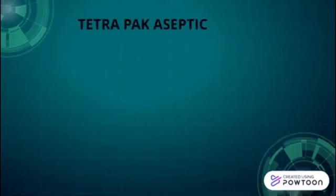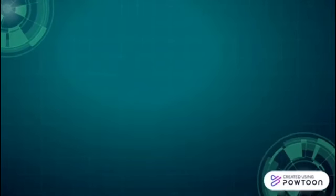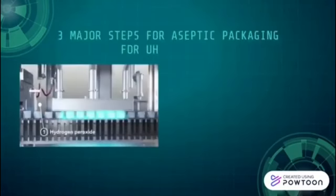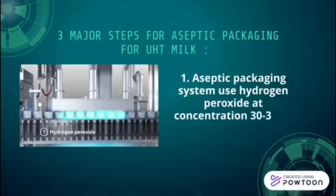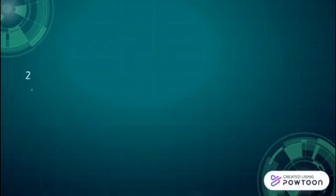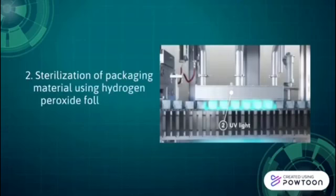Tetra Pak aseptic filling machine is one of the technologies used in processing and packaging for UHT milk. There are 3 major steps for aseptic packaging for UHT milk. First, the aseptic packaging system uses hydrogen peroxide at a concentration of 30 to 35%. Second, sterilization of packaging material using hydrogen peroxide followed by ultraviolet radiation.